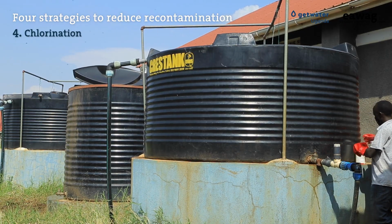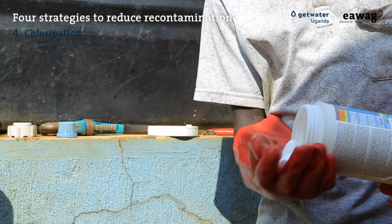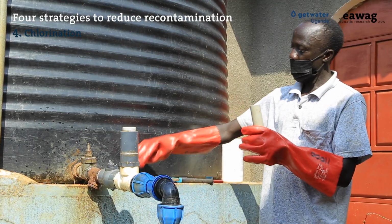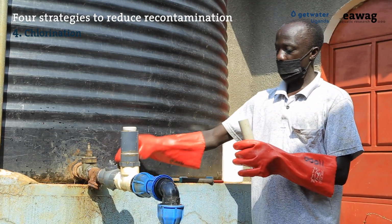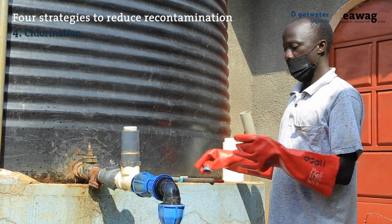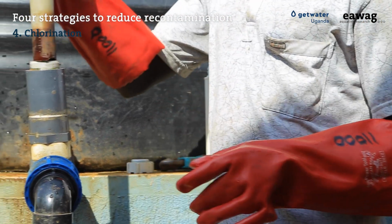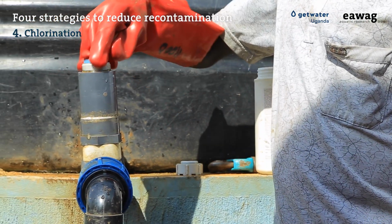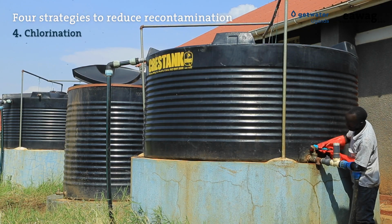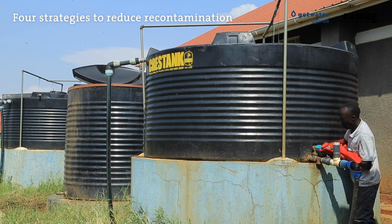To ensure that all water from the water kiosk is chlorinated, we recommend using a simple automated system-level chlorinator. There are different designs and technologies of system-level chlorinators. We recommend using a tee chlorinator that can be locally produced and which uses chlorine tablets. For further information, refer to the GDM manual.